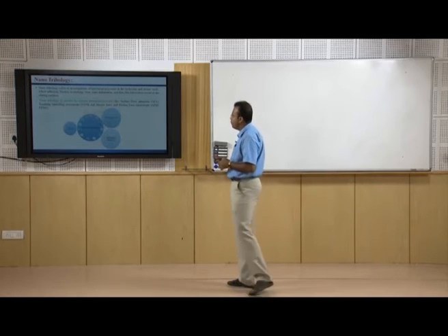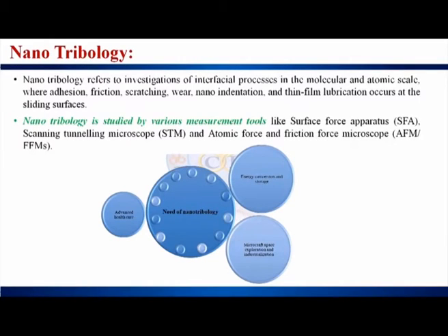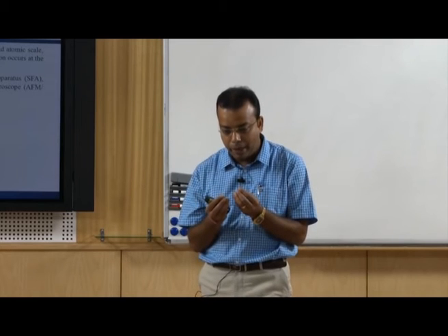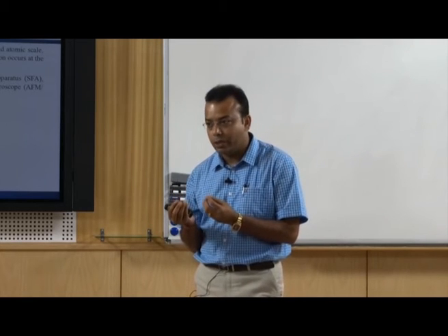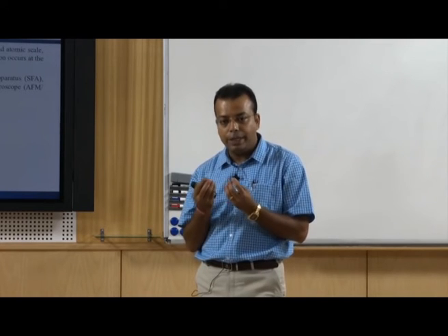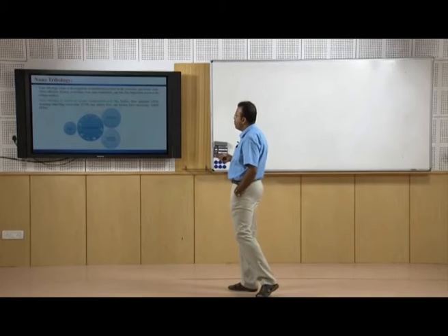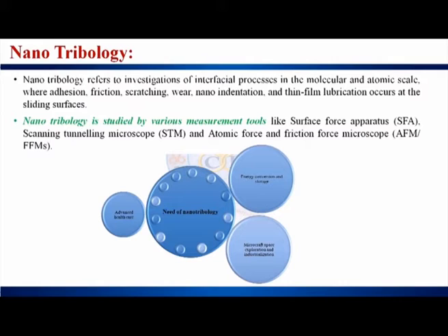nanotribology. Nanotribology refers to investigations of interfacial processes at the molecular and atomic scale, where adhesion, friction, scratching, wear, nano indentation and thin film lubrication occur at the sliding surface. As I already discussed, nanotribology deals with particles having very small dimensions. When small size particles interact with each other, that is known as nanoscale tribology. Nanotribology is studied by various measurement tools like surface force apparatus, scanning tunneling microscope, atomic force microscopy, and friction force microscopy.